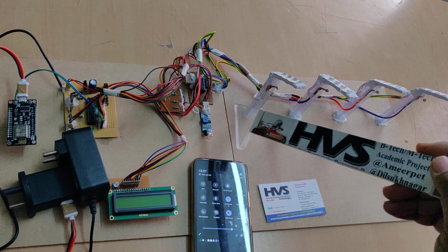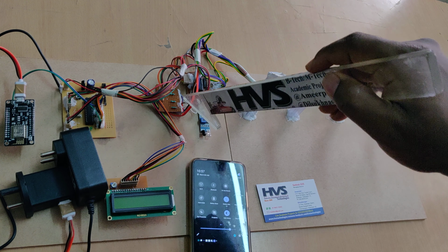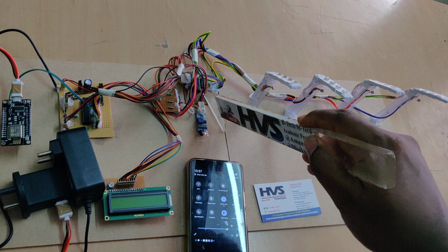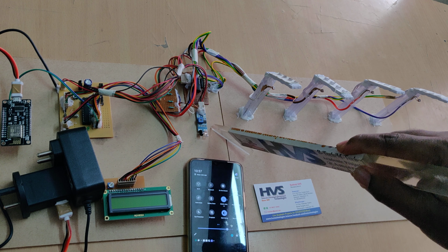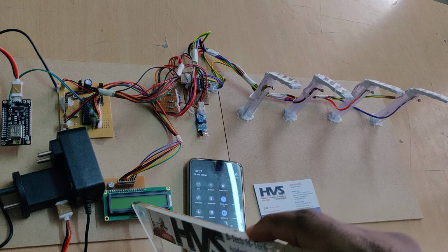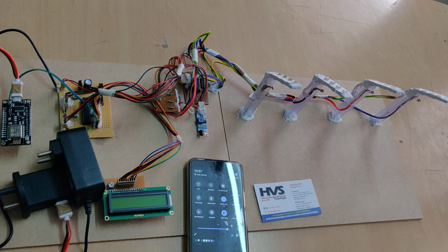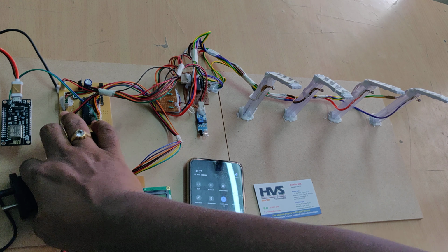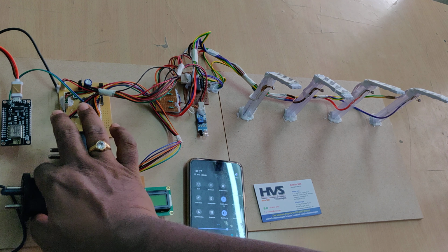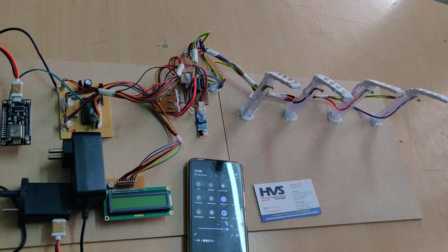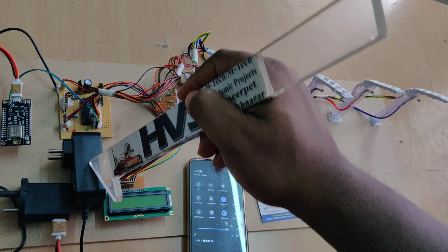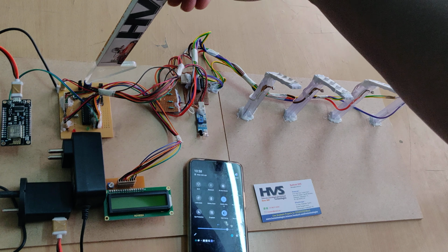So here, as we discussed, the LDRs interface to the microcontroller with this resistive driver board, and this ULN 2803 controls the street lights, the IR sensor detects the person, and the LCD displays the status. The whole system works on power supplies: one is a 12 volt power supply for the street lights and a 5 volt power supply for the Node MCU. As the Node MCU power consumption is more, we provide the extra power supply, and this 12 volts is given as the main power supply input to the motherboard.